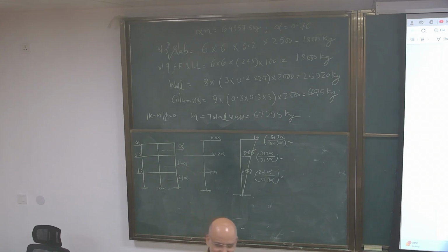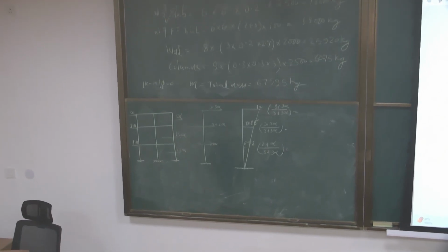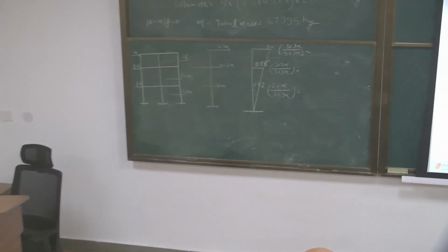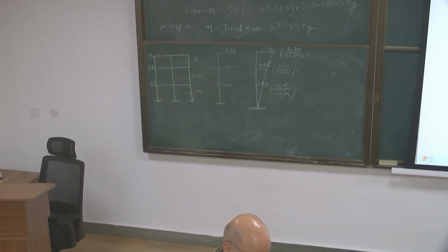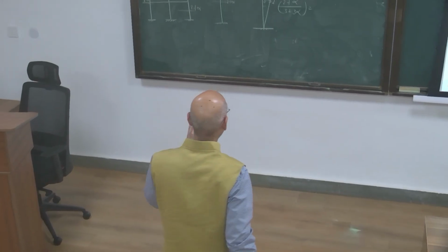So I can skip all that mathematics with large-size masses and everything, because if you see, the order of the mass is very large. If the mass matrix is assembled, there will be very large masses, and similarly in the stiffness matrix the numbers will be very large. So to handle those things, I made it very simple, either one or a fraction number, so you can easily handle it, as long as I am using linear deformations. So this is valid, but it has limitations.